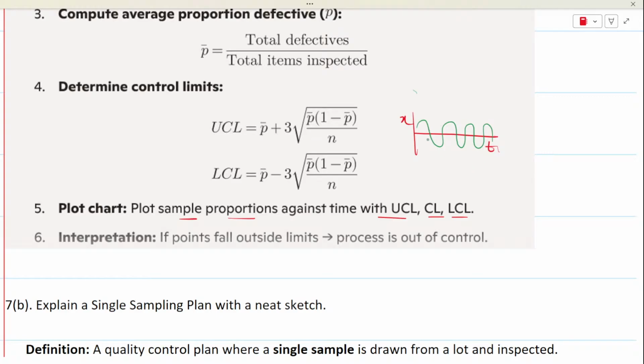That means with the inclusion of upper limit, lower limit and control limit, we are finding that the curve is crossing the average line. If the points are either on the upside or on the downside, then the process has gone out of control. So we have to recalibrate the machine in order to make the process stable.